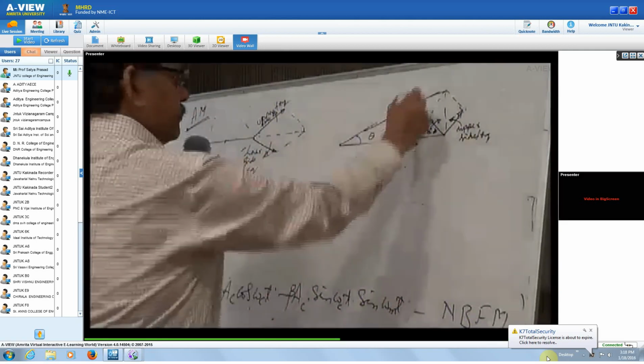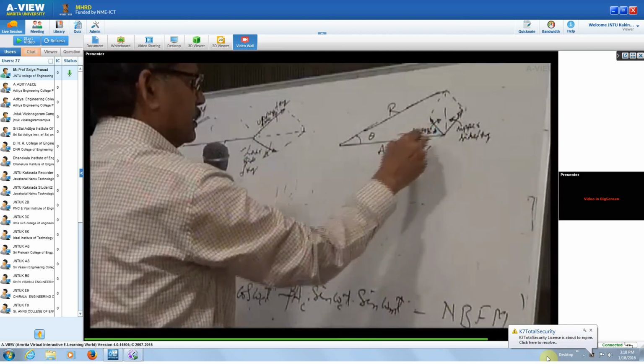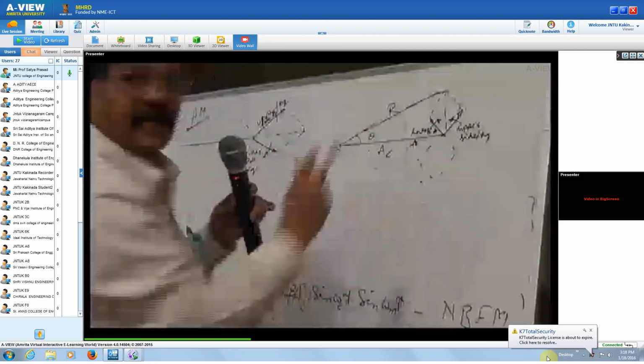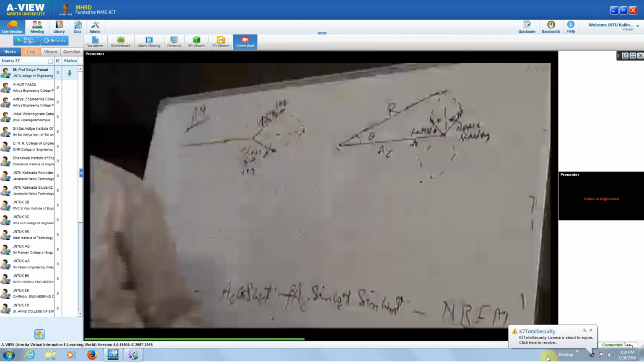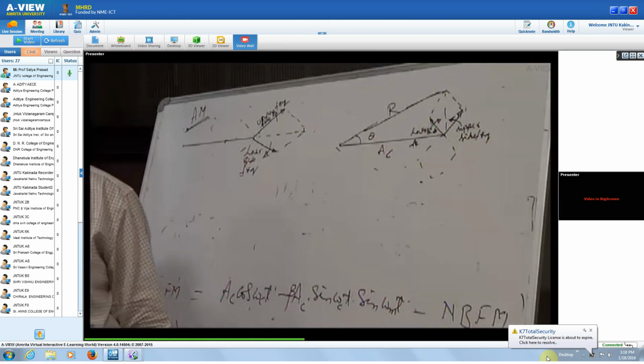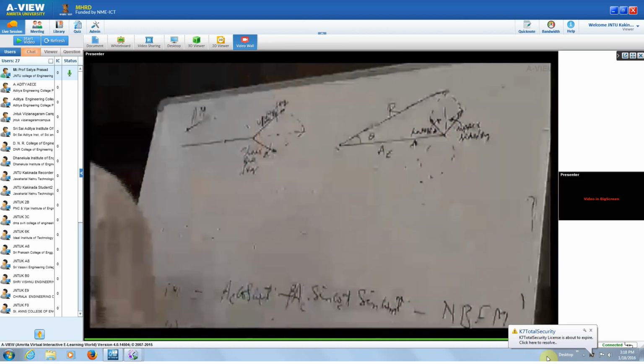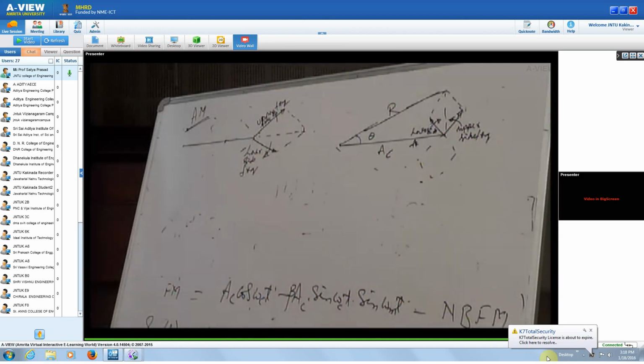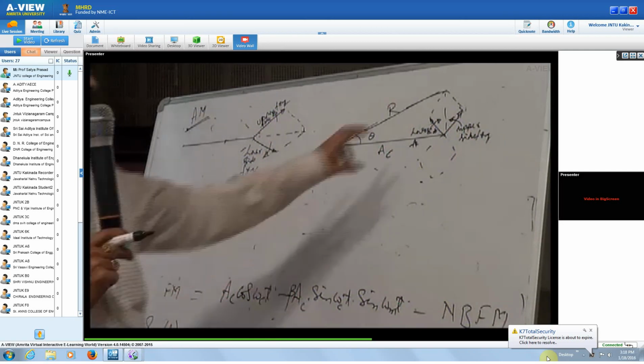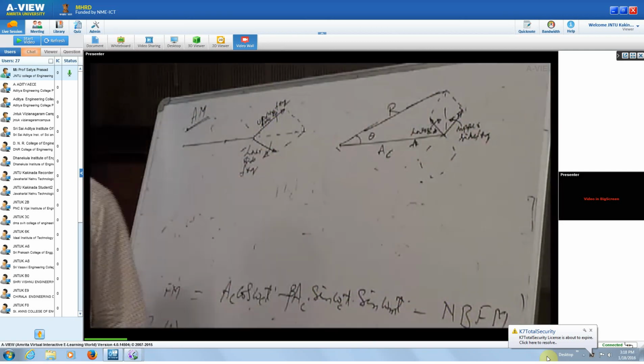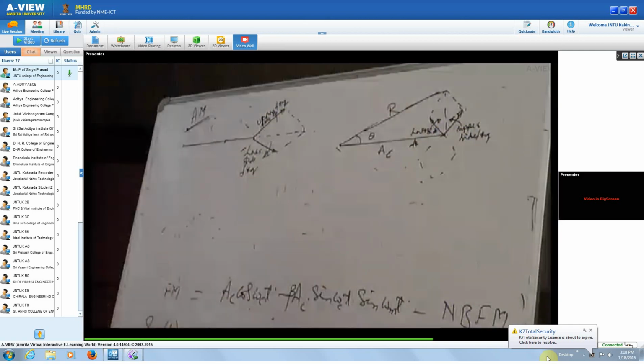It is varying. And if it comes like this, it may be coming here and so on. Positive and negative resultant values, phasors that we are going to have at different phase angles. Positive phase angle and negative phase angle. Maximum and minimum. So, your narrowband FM is not having a constant amplitude. Even though we are calling it FM, our narrowband FM is not of a constant amplitude.